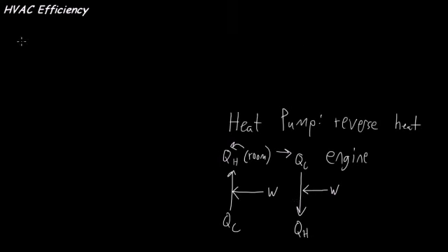Now the way we express efficiencies with heat pumps, and you have to be careful with that word efficiency. Sometimes people say efficiency with a heat pump, but what they really mean is efficacy. How effective is the heat pump at its job? Based on how much power or energy I put in, how much heat can I move from place to place? And that's measured with something we call COP, coefficient of performance.